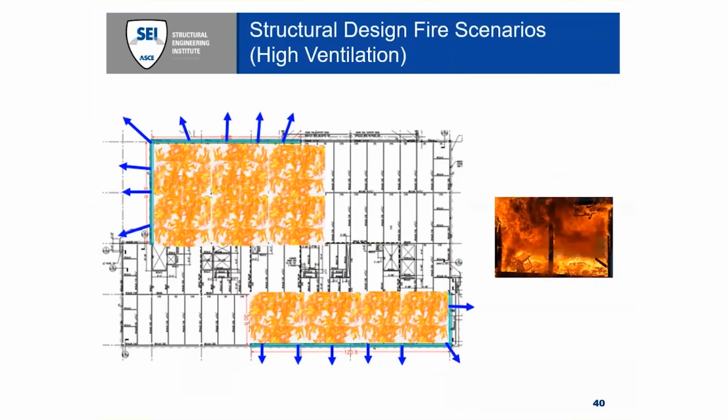In general, lower ventilation tends to extend the duration of the fire, but can also reduce its peak intensity by limiting the oxygen available to combustion. On the other hand, higher ventilation conditions can increase the fire's intensity, but can also allow hot gases to escape, thus reducing temperatures at the same time.